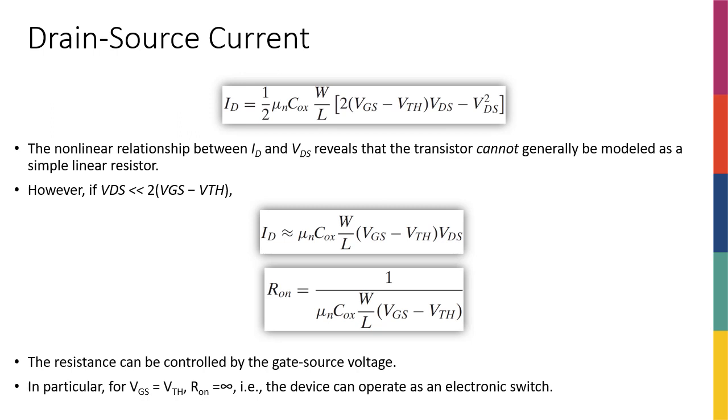Okay, now this nonlinear relationship that we found between the drain current, or the drain source current, and the VDS. So we're talking really about IDS versus VDS, right? We realized it's not really a linear relationship. So what we thought about the transistor being really a distributed resistor, at least generally, it's not really correct. It wasn't the correct assumption. It was kind of like a resistor, but if it was a resistor, VDS and IDS should have had a linear relationship, and the constant that was basically relating them to each other was the resistance, right?